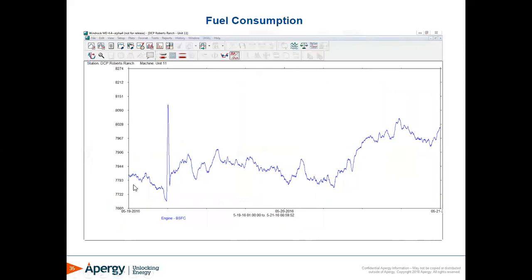So this is the fuel consumption during that time period. You can see that it's slowly rising over time throughout these 2 days here. So this is rising because whenever that peak firing pressure dropped down to compression pressure, the autobalance opened up that valve. So that would cause the fuel consumption to increase in this scenario. There'd be a sharp rise in fuel consumption during the event that would have continued without the online system.